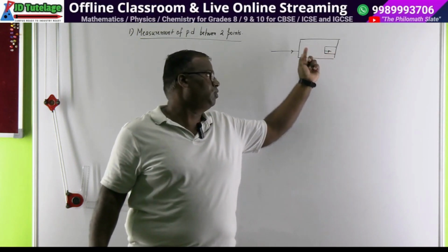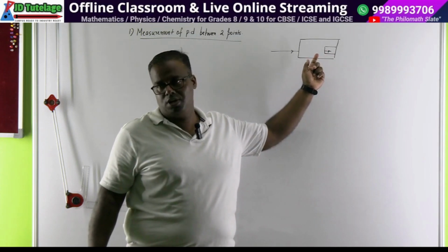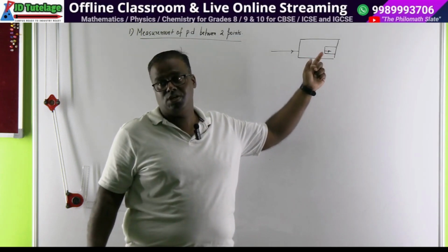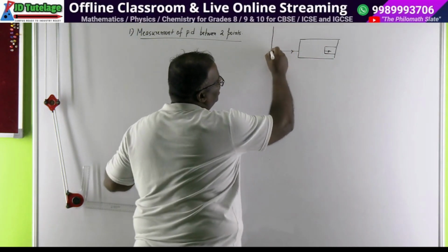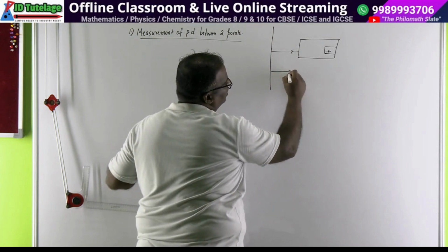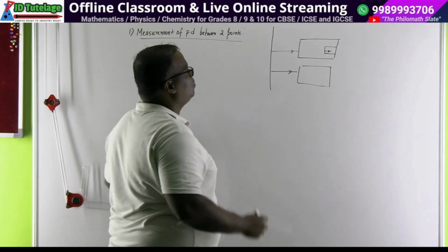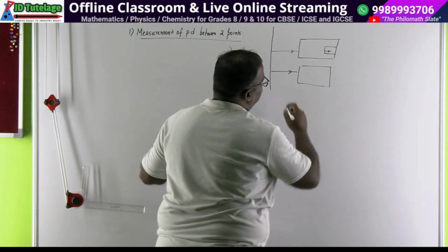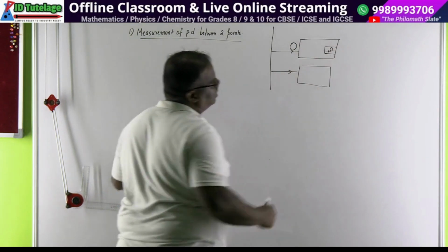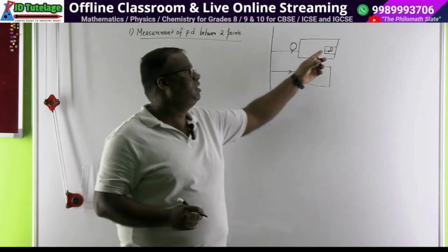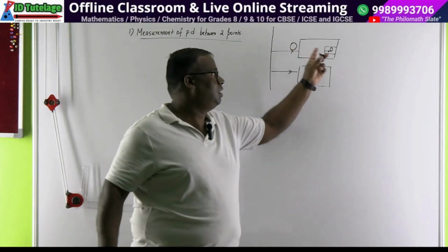And if all the bathrooms are having feeble pressure, then all you would like to do is ask your neighbor whether he is having pressure in this bathroom or not. So what is the common concept? A common header line will be coming. This will supply to the other unit also, another flat. Yes or no? So indirectly what you are trying to measure is, what is the water pressure here and what is the water pressure here. If you do not get any difference, then you should not have any complaint. When you are having a complaint, there will be a difference.